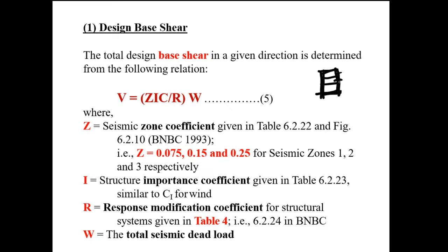In each of the stories there will be inertia forces, and the sum of those inertia forces that arises from each of the stories will be carried by this base shear V. So base shear is simply the sum of the inertia forces that arises from each of the stories.